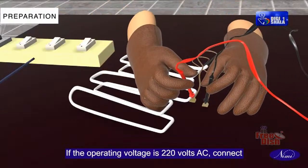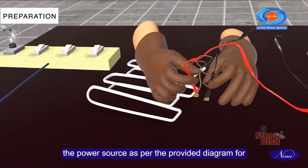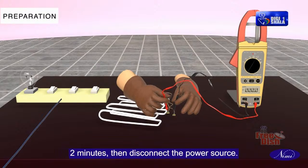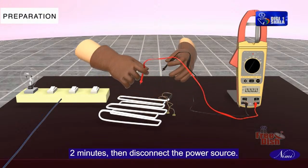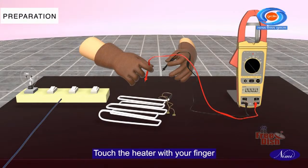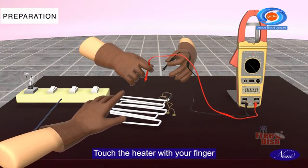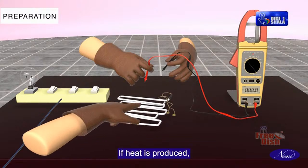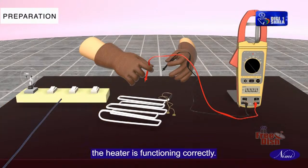If the operating voltage is 220 volts AC, connect the power source as per the provided diagram for 2 minutes. Then disconnect the power source. Touch the heater with your finger and observe if heat is generated. If heat is produced, the heater is functioning correctly.